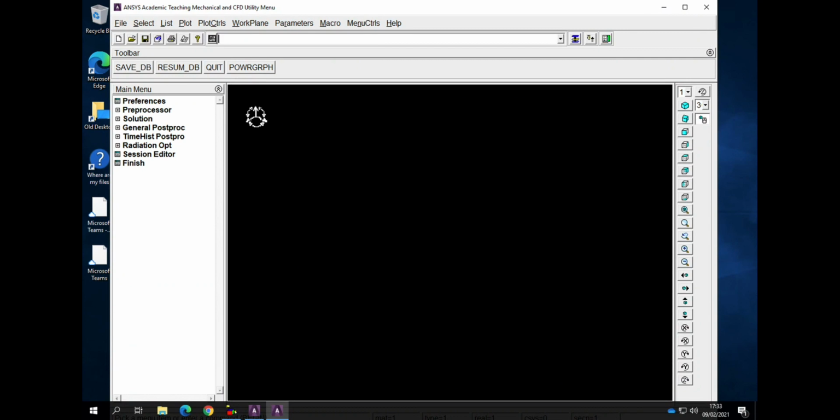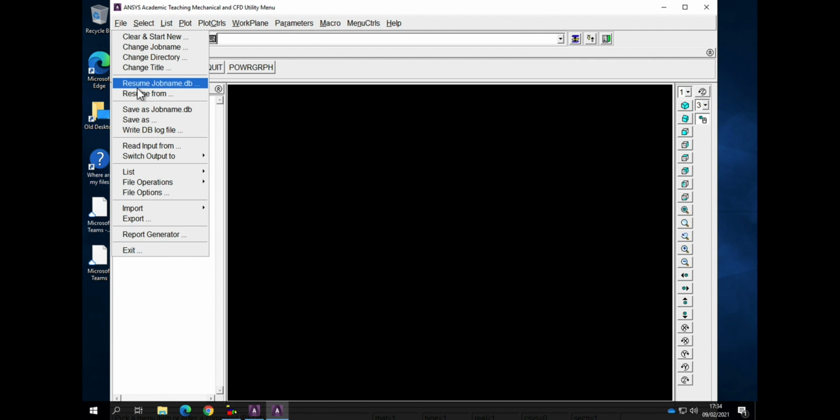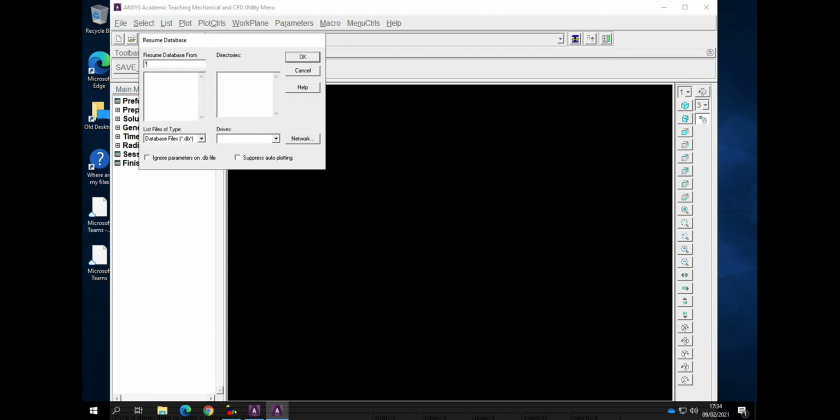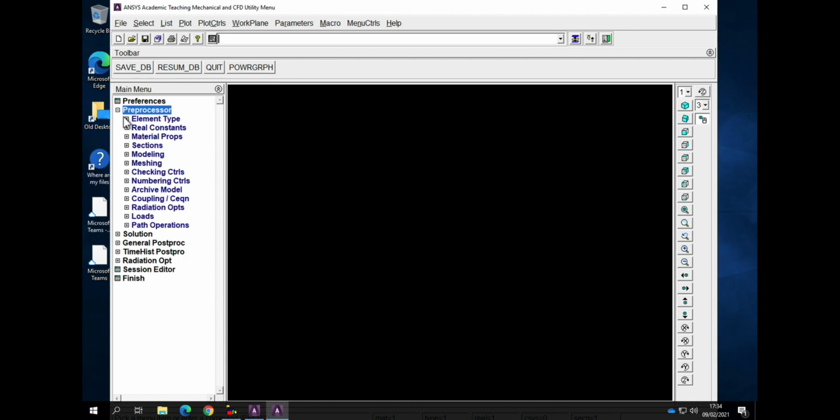Okay, so in the first example, we learned how to put in the stiffness matrix, the piezoelectric matrix and the permittivity of the material, and we learned the converse piezoelectric effect because we applied an electric field in the polarization direction, and we then looked at the corresponding strain. So in this case, we're going to use the direct piezoelectric effect and look at a voltage that's generated under applied load. So what I'm going to do is just resume from inputting the materials properties because we did that in the previous example. So I'll just load in the properties just to quickly recap.